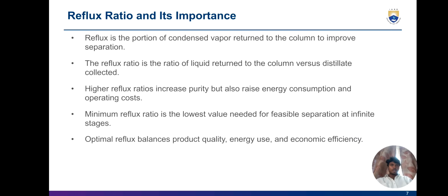Reflux ratio and its importance. Reflux is the portion of condensed vapor returned to the column to improve separation. The reflux ratio is the ratio of liquid returned to the column versus distillate collected. Higher reflux ratios increase purity but also raise energy consumption and operating costs. Minimum reflux ratio is the lowest value needed for feasible separation at infinite stages. Optimal reflux balances product quality, energy use, and economic efficiency.